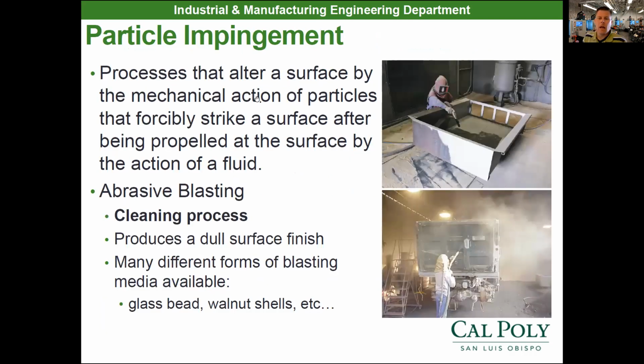The first one, I mentioned this as a way of cleaning, but it's also a way of changing the surface of your part, and it can also change the mechanical properties of your part. It's known as particle impingement, or abrasive blasting. With abrasive blasting, we're using air pressure and a high flow rate of air. Along the way, we have a little Venturi effect where we pick up some glass bead, walnut shells, or some sort of abrasive media to impinge against the part.